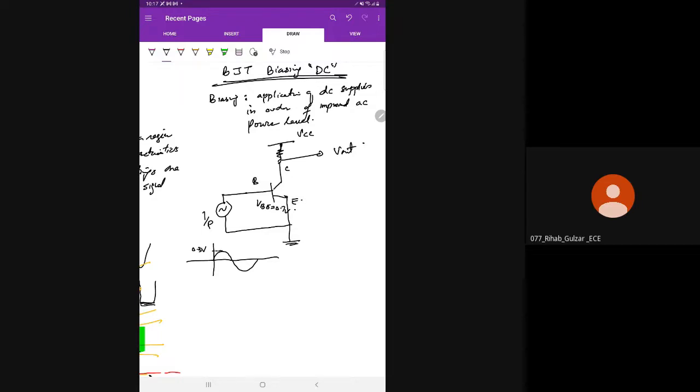In order to make it detected, you have to add at least, कम से कम इसको 0.7 DC हमें ऐड करनी पड़ेगी, तब जाके ये बनेगा शिफ्टेड AC. अब आपकी बनेगी यहाँ 0.7 वोल्ट और सिग्नल ऐसी है. 0.7 प्लस 0.3 मीन्स 1 वोल्ट, 1.0 वोल्ट, और यहाँ होगा प्रोबली 0.4 वोल्ट पीक टू पीक. ठीक है. अब अगर आप ये सिग्नल इनपुट पे, VI इनपुट पे अप्लाई करेंगे, तब जाके जब सिग्नल यहाँ से यहाँ जाएगी तो पॉजिटिव हाफ इसका क्रॉस करेगा VBE को, because it will cross 0.7.